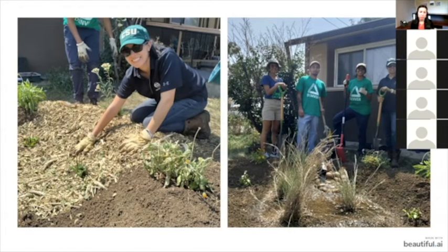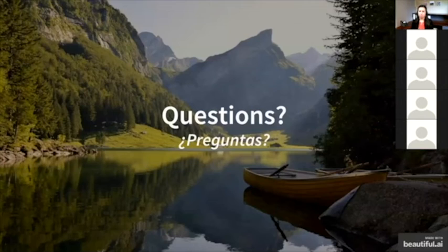Now here in this picture, this is chipped mulch versus shredded mulch. And so I would recommend using shredded mulch instead. But for this particular project where cost is a concern, using chipped mulch will work as well. And what we talked about during this project was if you see that you're having a lot of issues with your mulch moving, then you can change to shredded mulch.